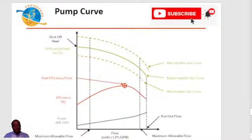This is how the curve looks for either a rated or maximum impeller diameter. As the flow increases, the differential head decreases, and as the flow reduces, it increases. That is how a centrifugal pump behaves.